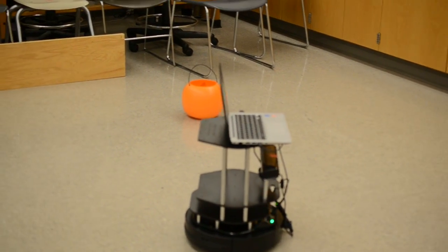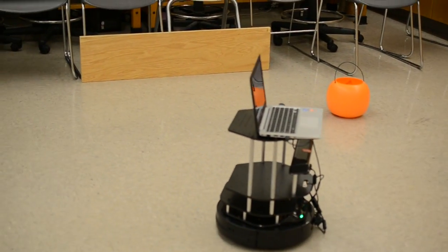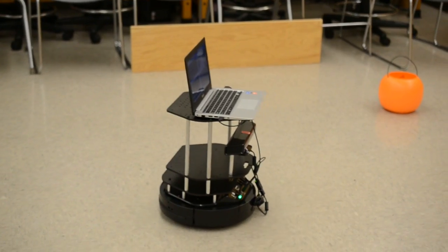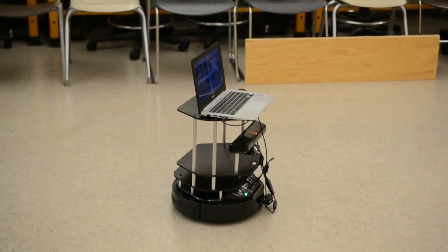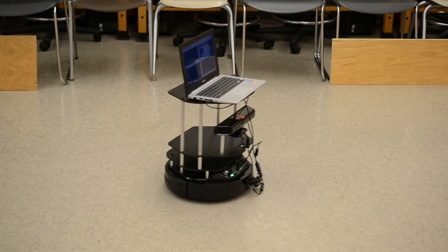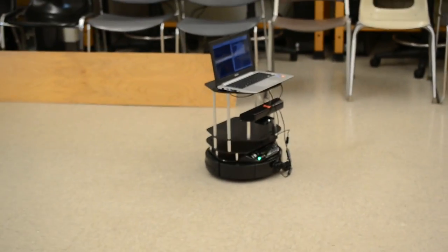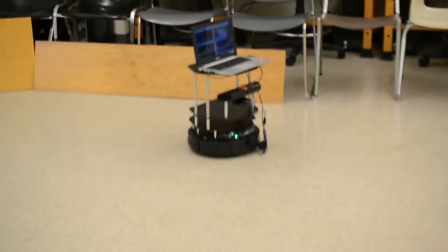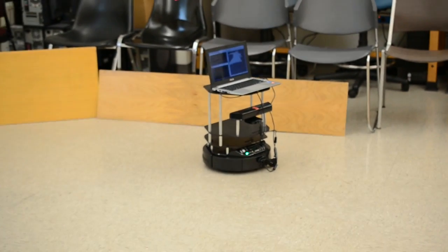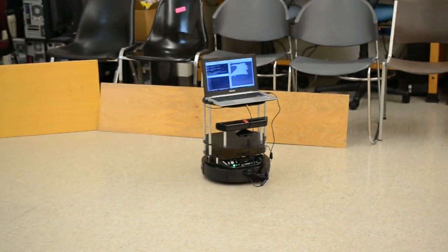It converts the center point to an XYZ 3D point in the camera coordinate frame so that we can view it in actual space. It publishes all the pumpkins it currently sees as a marker array to a topic so that you can pull it up in RViz and view it in relation to the robot.